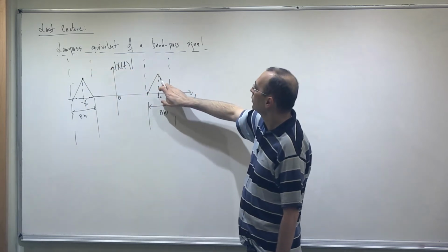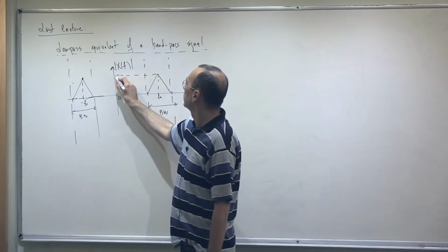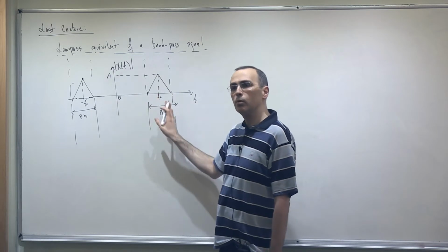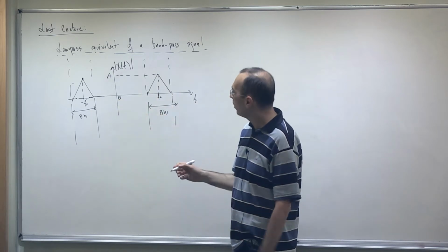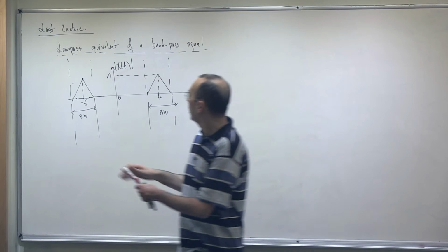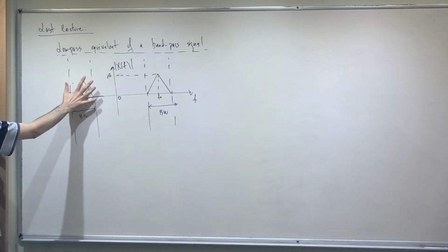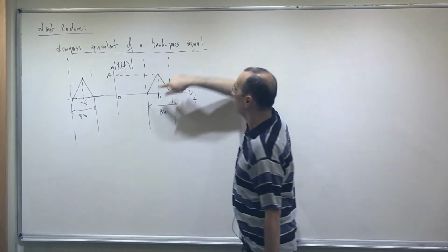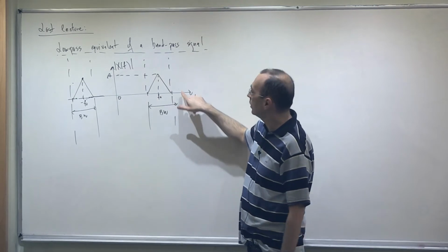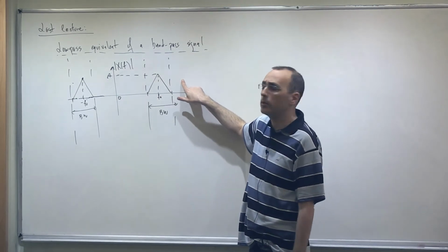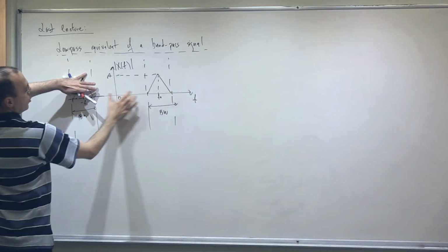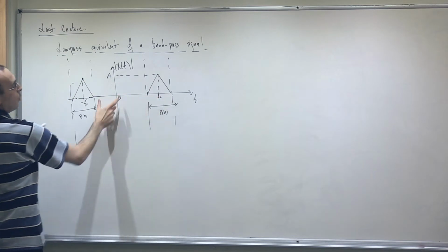So the low-pass equivalent is essentially, you would like to shift this part only to the origin. So you would like to make this low-pass. So how can I do this? There are two steps. First you get rid of this negative frequency part. Once you get rid of this negative frequency part, the remaining signal with the non-zero values at zero and the positive frequencies is called the analytic signal. You may remember, it's very important, analytic signal. Then you have only this part, then you move it to the origin, that becomes the low-pass equivalent.